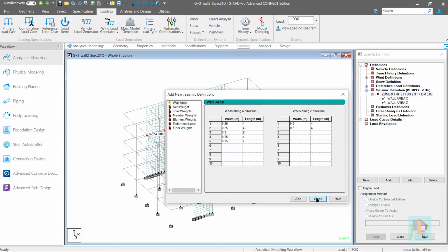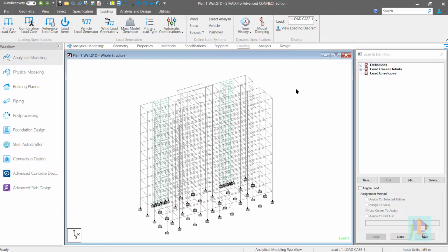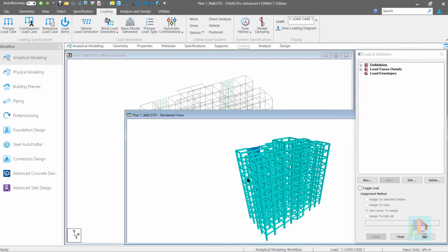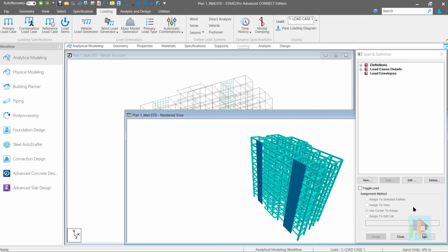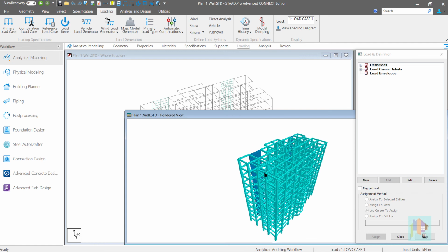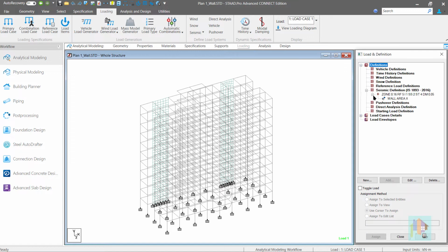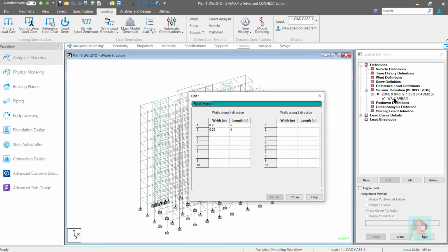Dimension of all existing concrete wall in the first story is provided, and the program considers this wall data to calculate the time period as per clause 7.6.2b. Use of different type of framing system in different direction is quite common. For example, in this model, there are few concrete walls in X direction, but there is no wall along the Z direction. Construction cost of a concrete wall is quite high, and we need to use these walls only when it is required. For this type of framing system, we need to provide required wall dimension in X direction only and skip any data along the Z direction.